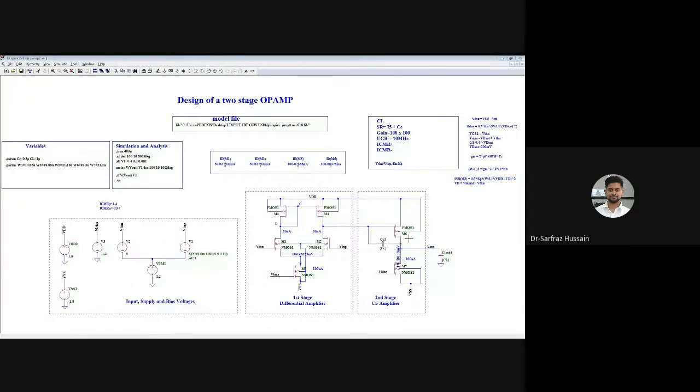Now, what are the values that we already know in this particular transistor? Or we can do a matching also. How can we do the matching? This current and this current, this width and this width. So we can do this kind of matching: the current flowing through this divided by the current flowing through this will basically be twice, because this current is twice the current flowing through this one. So we can use that property.